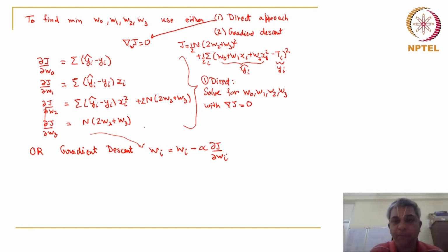Notice when I do that, I am updating both the weights which are sitting in the temperature as well as W3, which was my volumetric heat transfer. So notice that this parameter, which we don't know, is also getting updated during gradient descent. So suppose you do the fin problem, your parameter m will also get updated along with the weights. I find it's a really neat method. You solve for every parameter along with the inverse problem that you're solving for. You solve all of them simultaneously using gradient descent. You update, and you end up at the solution.